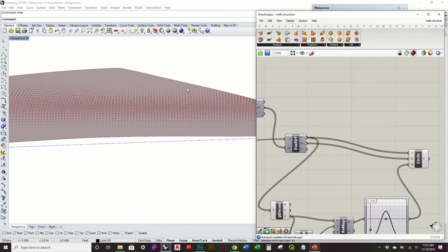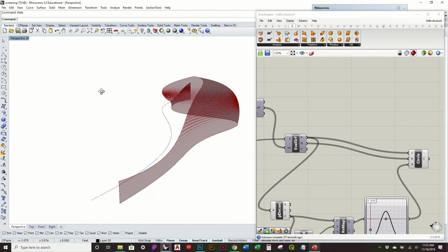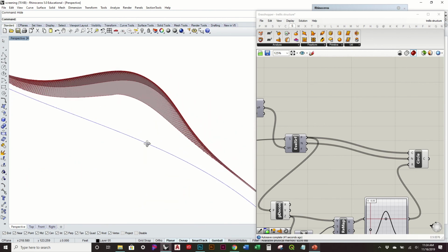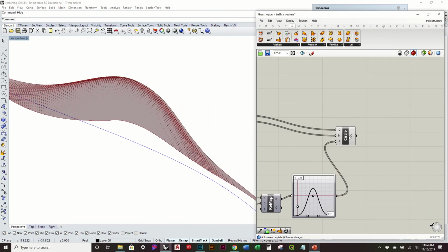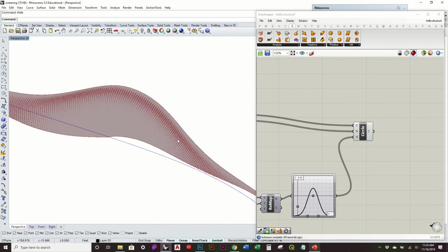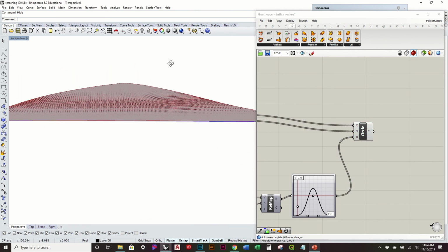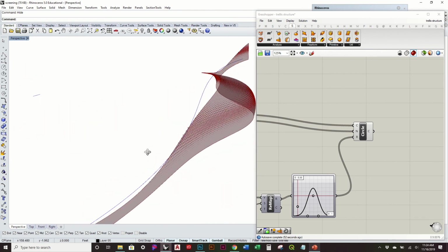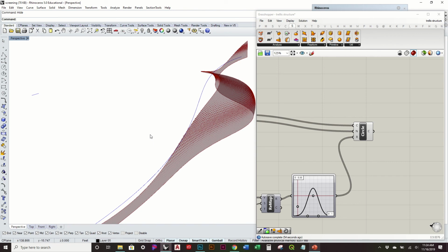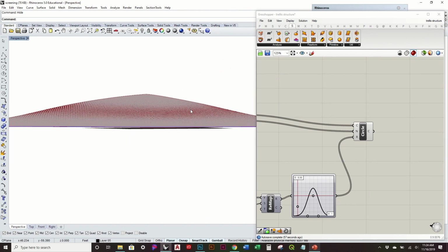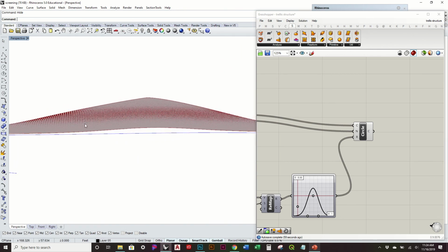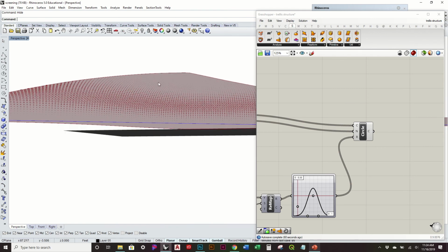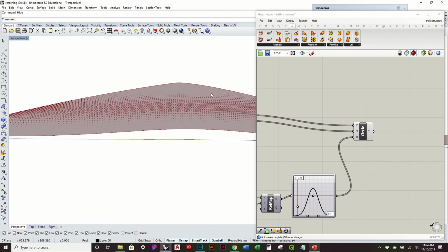So now I can obviously begin to bake this and split the surface using this perforation. It does require quite a bit of effort, so I'm not going to do it in here, but basically what you would do is bake both the surface and these curves to create that actual screen. So that's what you can do from there. We'll look at other examples where maybe it's not just this kind of pattern of points, but actually using an image as well.